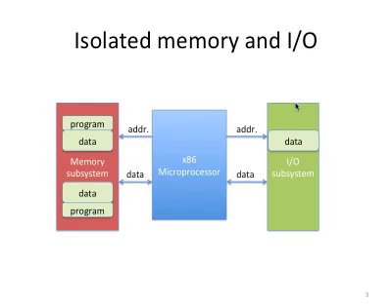You can put these two subsystems into two separate memory spaces. By memory space, we mean an addressable region, starting with address 0. So when you put the memory and I/O in separate address spaces, they both have starting address 0 and go up to their maximum address, depending on the size of the space.